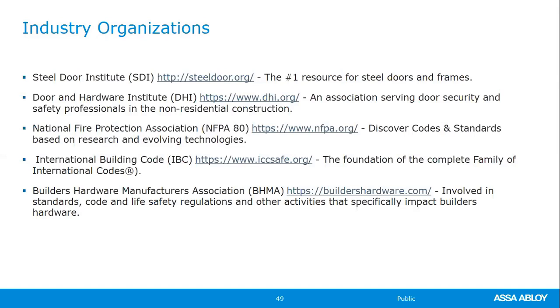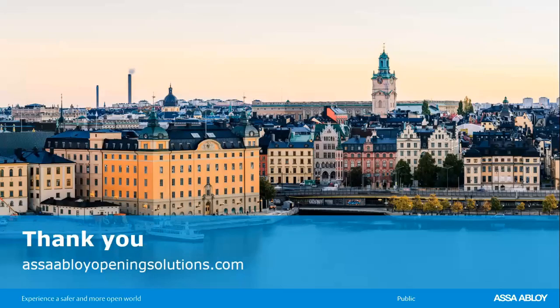That's where you'll see listed in NFPA 80, if you have a fire rated opening or door in a frame, the biggest modification you can do on a fire rated field door frame, which is a 1-inch diameter hole. Anything other than that, as far as modification of a fire rated frame in the field, has to come back to that distributor, or someone licensed to modify it. Your IBC, also your BHMA. These are different organizations that you'll see day in and day out in the specifications. So with that said, that will conclude our overview of steel frames.